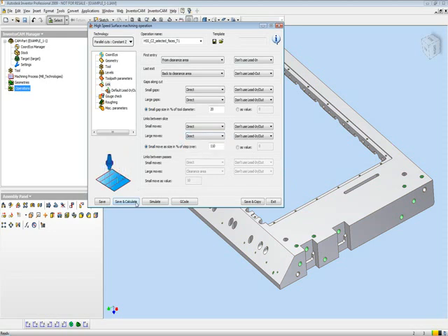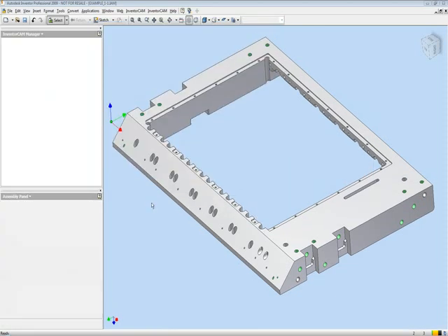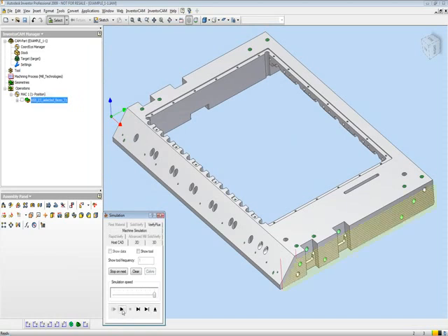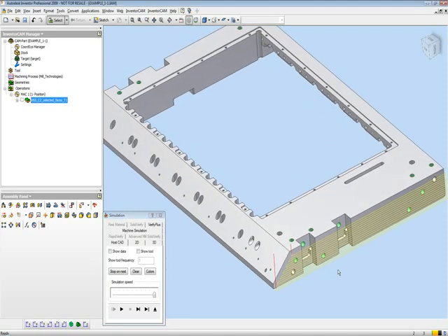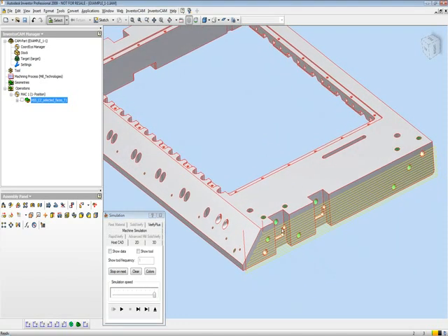Now let's take a quick look at our simulation after I do my save and calculate, and you'll see that the toolpath is going directly over the surface itself as if there was one whole complete surface, not jumping over or sinking into those surfaces at all. Now what I'd like to do here as well is take the end of my toolpath over here and extend it further out so it doesn't stop exactly on the corner here, and the same thing on this side as well.